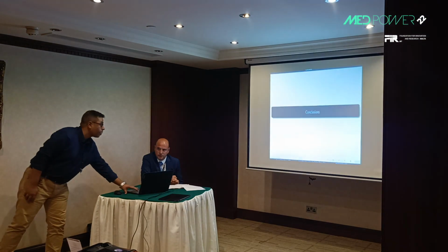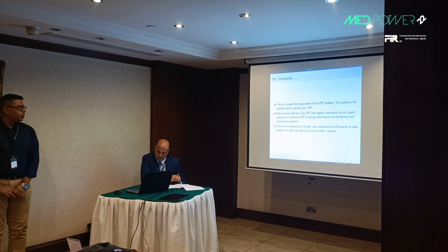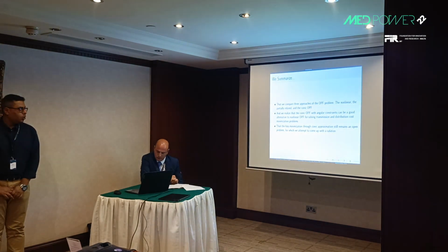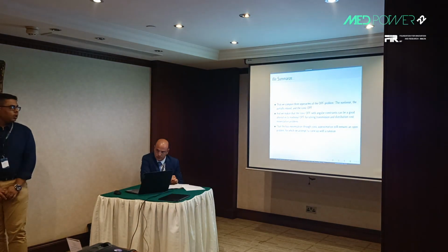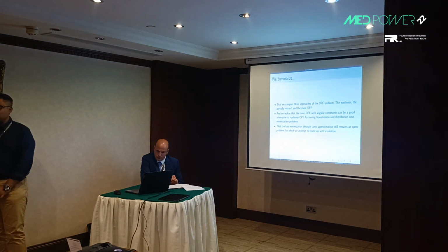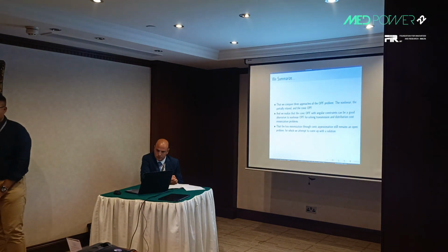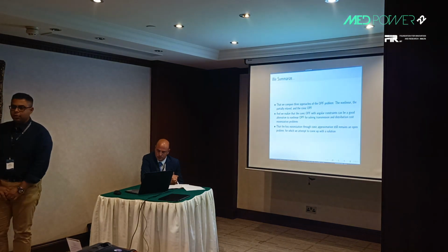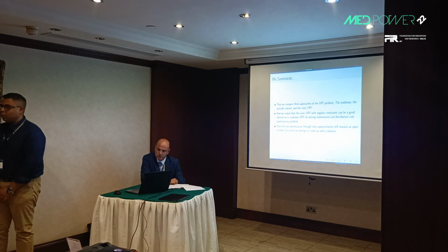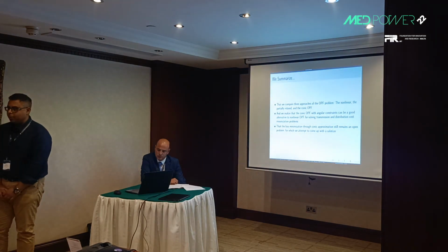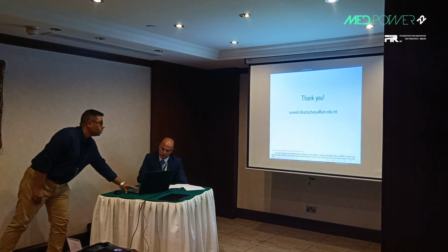To conclude, we have compared 3 approaches to the OPF problem: the nonlinear, the partially relaxed, and the conic OPF. We see that to have good agreement with the nonlinear OPF, we can use conic OPF with angular constraint. Although it's polynomial, we yield a very quick result with it. Loss minimization with the conic OPF is still an open problem, and we are looking to come up with a solution for this. Thanks.